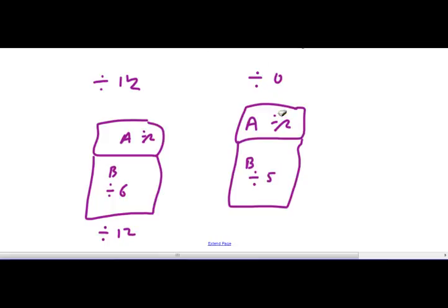And those, if we put them together, we can have a 10. But if we only came in the B clock and we came out QD, we would have divide by 5. So to get it to go up more, if you only had the B, and if you went into QA to QB, would that be a divide by 10 since you went in that twice?